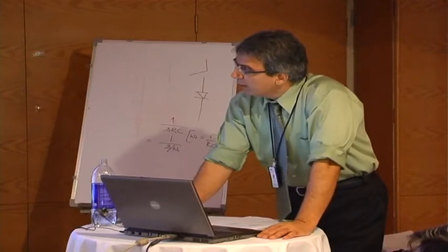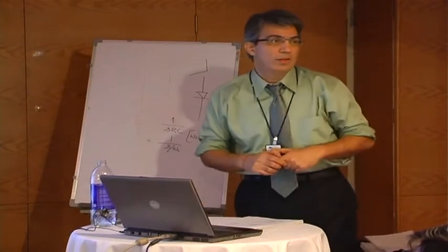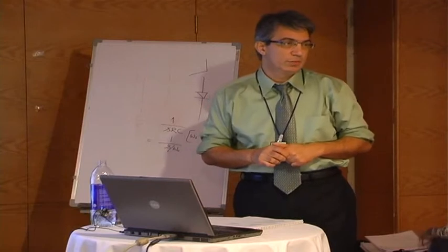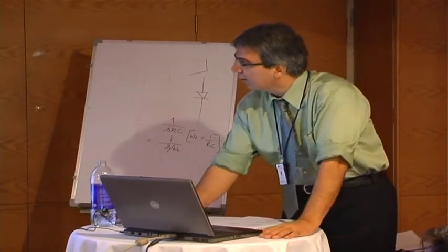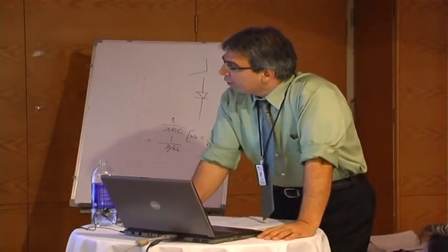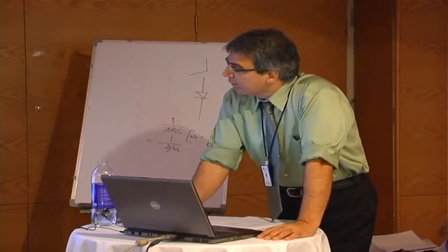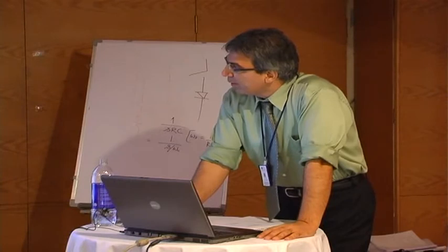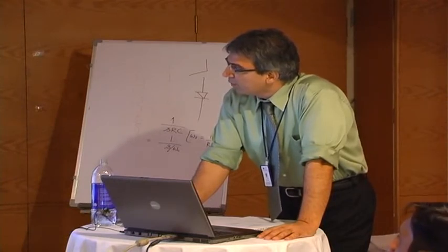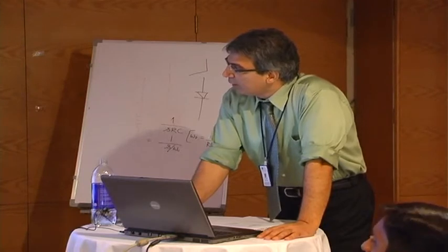And now this is where you can mess around with options when you have convergence issues. You can play with the relative accuracy of voltages and currents, which is 1 millivolt here or 1 milliamp here. The best accuracy of voltages is 1 microvolt. Best accuracy of currents, 1 pico.